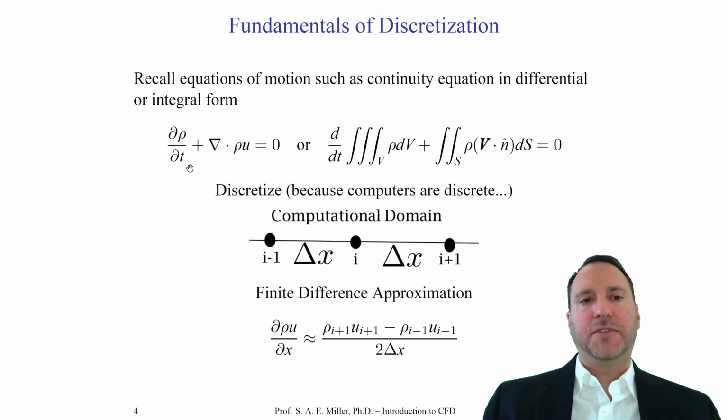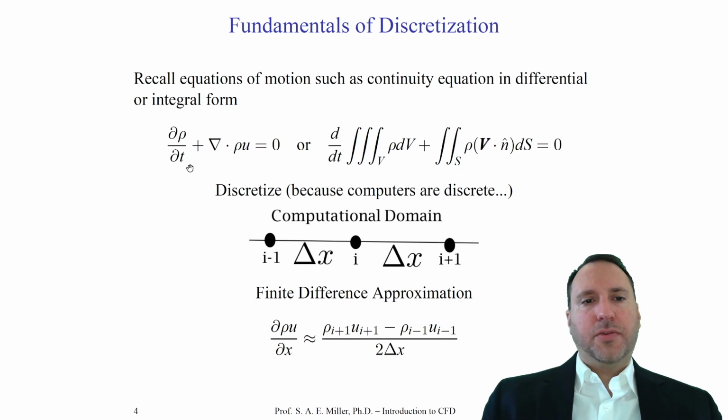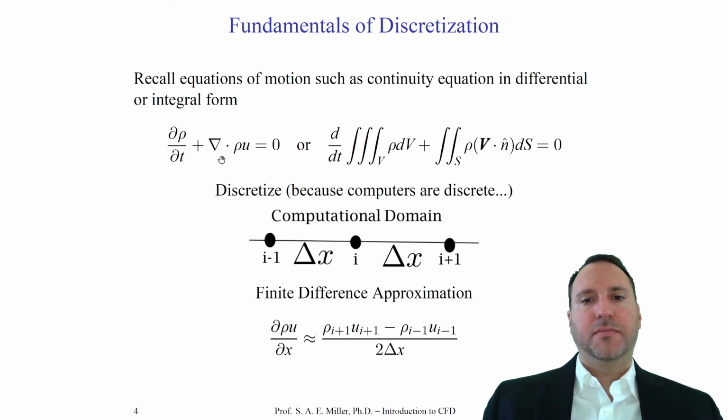The approach on the left is actually used much more typically in the so-called finite element or finite difference solvers. Now, these equations are both in their continuum form. If we want to solve them in a discrete framework, numerically, on a digital computer, they must be discretized, and we have to have solutions to these equations everywhere in the domain for them to be valid and hold the boundary conditions. We can check their solution by finding the residual of the numerical solution.